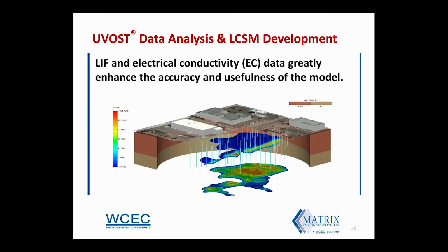Now, this slide is a pretty typical ISV deliverable. This has a lot of components. You can see we've got an aerial photograph that is overlain on a geologic surface. You can see we've got a sand and silt layer. Those are identified using the EC probe.